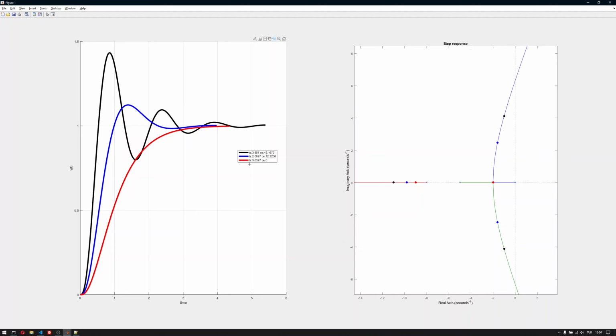So choosing the settling time like 2-3 seconds is ideal for a system, but having slower settling time values, or higher values for the settling time and slower closed loop systems, does not really make sense for this system. Overshoot increases, settling time increases. What good is this system?